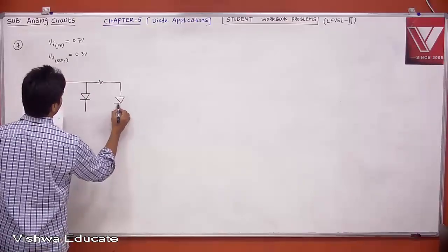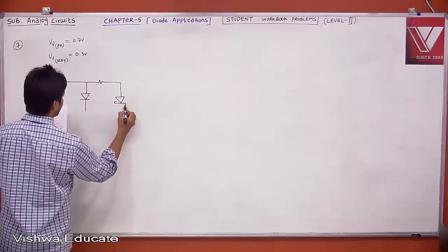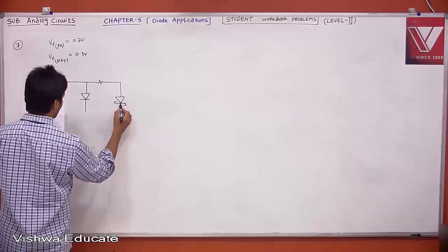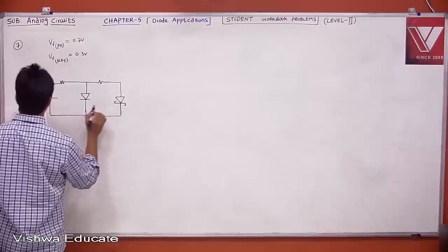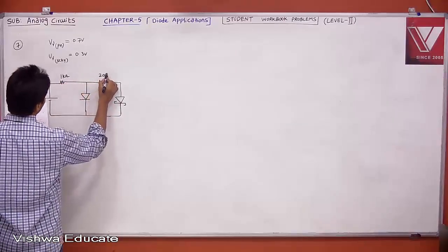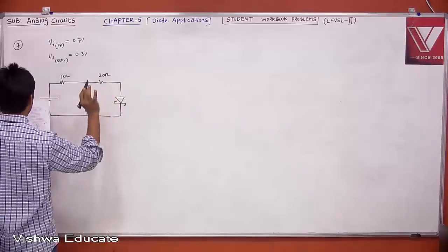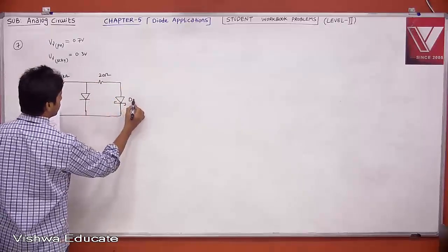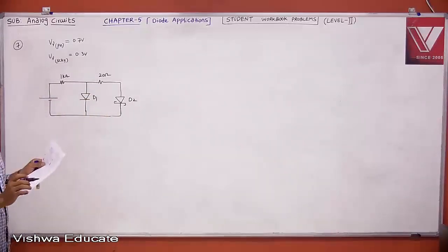This is Schottky. A Schottky diode is one side metal and the other side semiconductor. Its cut-in voltage is different, but when you solve the problem, think of it like a PN junction diode having a cut-in voltage of 0.3. You just think in that way. This is D2. D1 has both semiconductors, P and N, a PN junction.